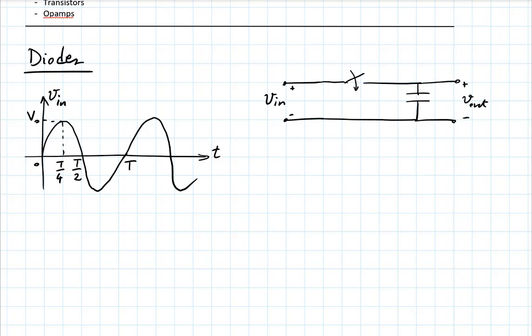So we're talking about a scale of several milliseconds control. If you could do this fast enough and close the switch at time 0, and after 6, 7 milliseconds, whatever point T over 4 is, disconnect it, you would see that constant output voltage on the capacitor. Now you might say, well, that's good. And that is kind of the essence of what we are going to be discussing for the next couple of weeks. I think you would agree that it's not practical to put someone in charge of closing and opening that circuit like that. So that's one issue we have to deal with.